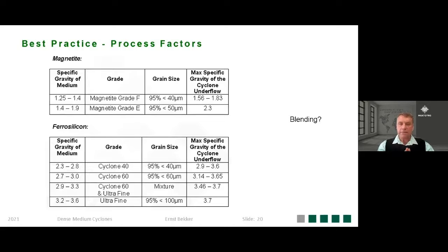But keep in mind, when you go now to your magnetic separator, the ferrosilicon and the magnetite have two different magnetic susceptibilities. The ferrosilicon is normally the stronger one. So the magnetic separator will recover all the ferrosilicon, and if there's space available, it will recover the magnetite. Maybe it's not so clear cut, but I think you get the picture.